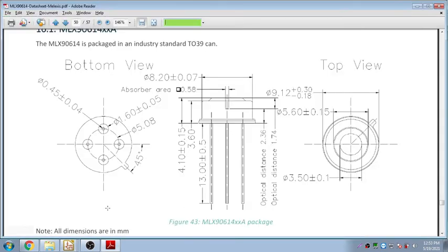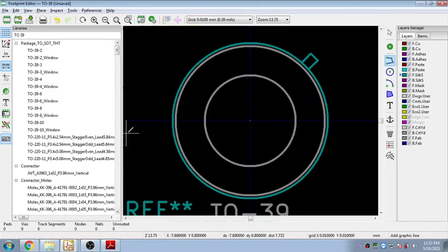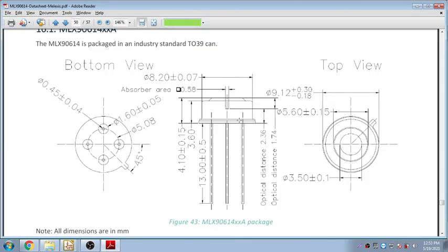And if you want to make a further, let's go with the bottom actually, where we need to place the pad, and we have to be careful when we are deciding the pin numbers for this. So we will start exactly by putting the marking here. We are exactly at the origin, so it is easy for us to give an exact position for this. So it is at the x-axis, this is 5.08, that is actually the diameter.